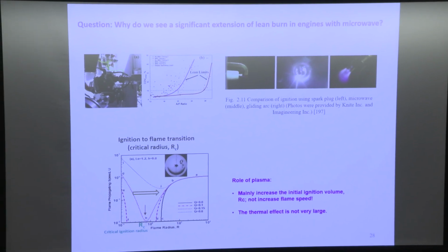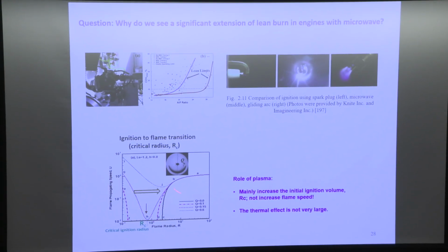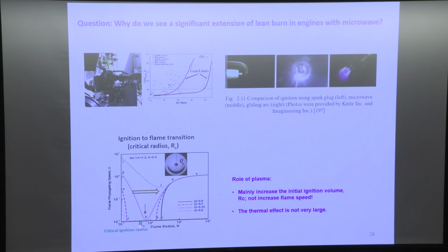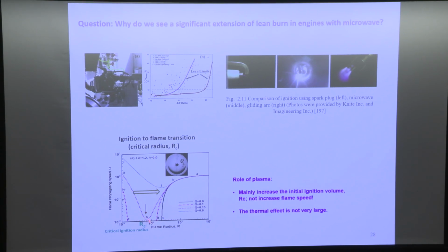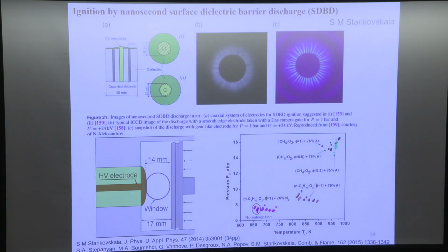This matters because even though the mixture is flammable, if you cannot drive the initial ignition kernel bigger than this critical radius, you cannot ignite it. This gives a very clear guide to design a future igniter using plasma to drive a spark or a discharge. If it's bigger than R_C, then you can always successfully ignite it.